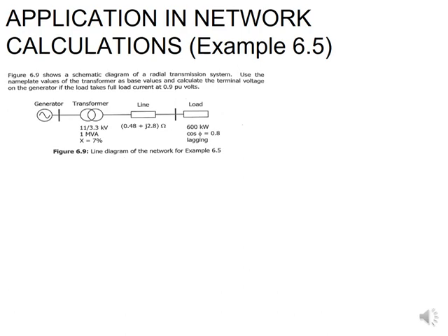It means that number one, for our generator, we can't make an assumption that it's also sitting at 11 kV. As we've learned, your generator is not always at the same voltage as your transformer, hence we need to calculate it. The second part that they're telling us is that you've got 0.9 per unit volts that you are going to utilize as the voltage at your load side.